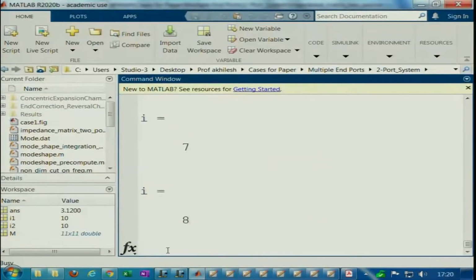So, you will see a flow reversal kind of behavior, and there are a lot of parametric studies that you can do on your own. So, let us demonstrate the behavior for a long chamber muffler configuration. It is going to take a minute or so, and we will also analyze the case where we have the plane wave mode. So, you put m is equal to 0, n is equal to 0, and we can see the deviation, what the end correction does, what we were discussing all this while.